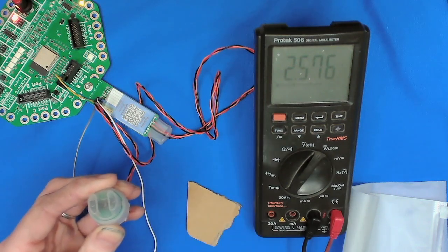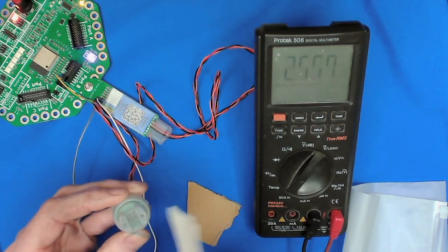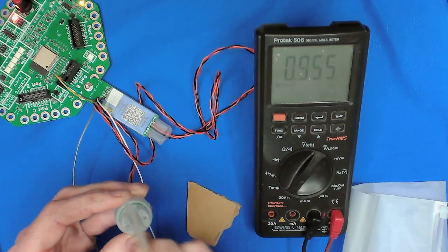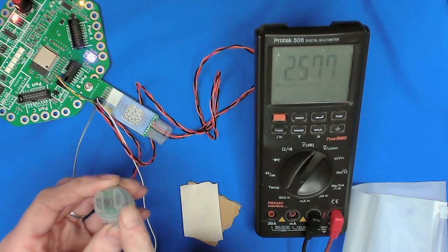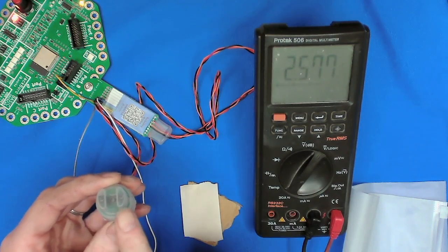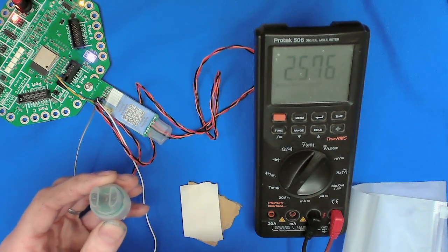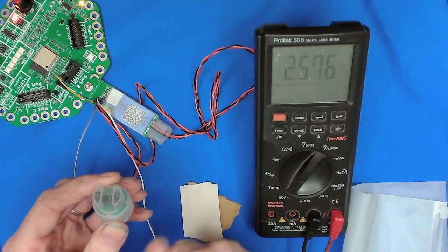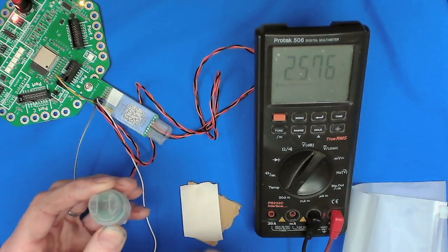So once again, you have the transmitter on one side and the receiver on the other side, and the sensor is looking at how much infrared light can get through between the two parts. The reason they use infrared light instead of visible light is that if you were to use visible light, then you would end up detecting lights in the room, you detect the sun, you detect all sorts of things. So they use infrared, which you can't see, and it gives much better readings.